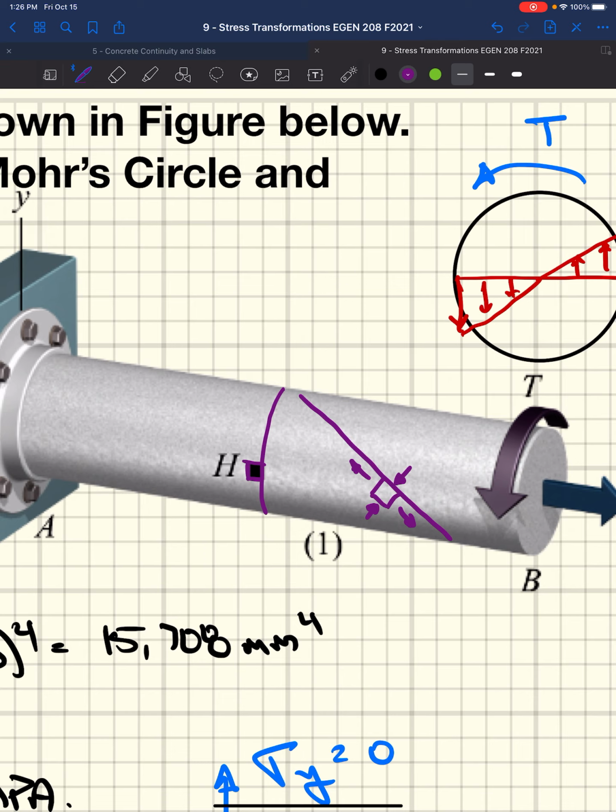And that's why, setting the axial load aside, I can take a piece of chalk, or we talked about some failed shafts earlier on when we were talking about torsion. That's why when you twist a piece of chalk, its failure is a spiral as it runs around the shaft, because its principal stresses are actually oriented at, in that case, if you don't have any axial load, 45 degrees. And so you get this pure tension, and so the shaft wants to essentially pull itself apart at an angle, even though you're twisting it.